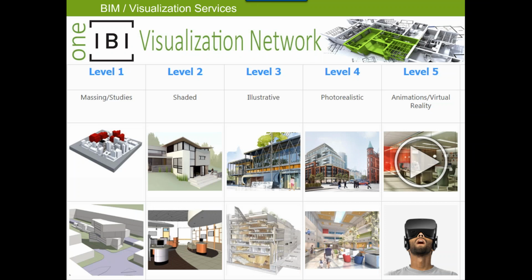And we divided this into 5 levels to say, look, those first 3 are really within the control of the design teams and orchestrated by the BIM coordinator. Levels 4 and 5 get you into the Max world or other tools that help facilitate different types of workflows. This isn't cast in stone. This is just a guidance leveling that we do internal to IBI. But as a BIM coordinator, just conceptually understand that if I want to generate a view like this, most likely I just need a 3D view in Revit, and I hit the Revit engine rendering and away I go. Here in level 3, I may have V-Ray or Enscape tied to my authoring tool, and I do something like that. Or I may start to feed it off to a Viz expert, in which case a workflow would have to be looked at.